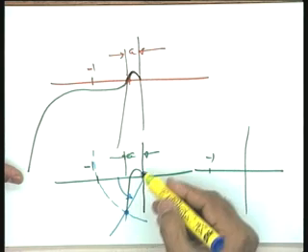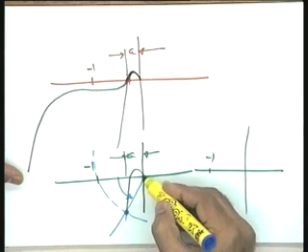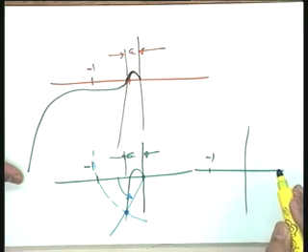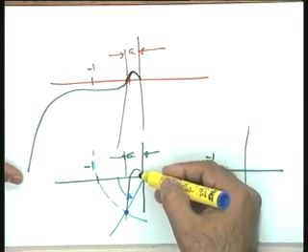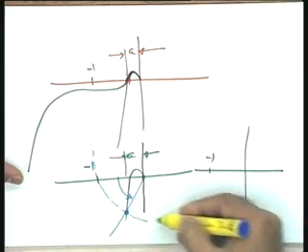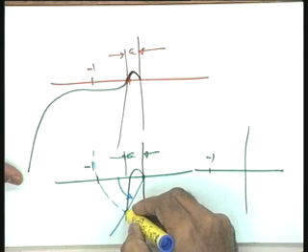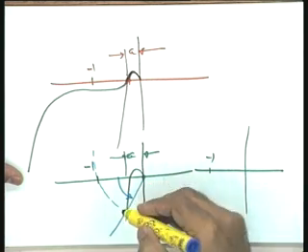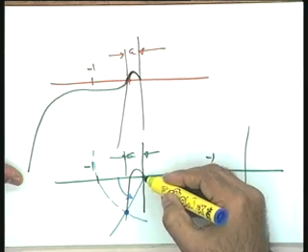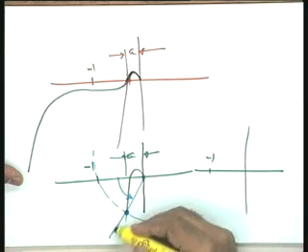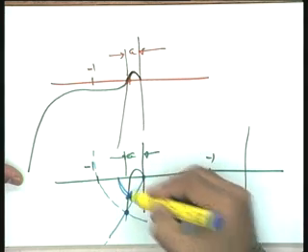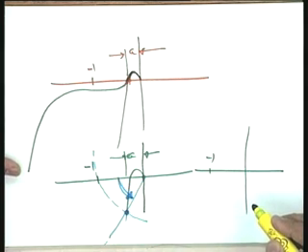I again repeat, the point on the plot where the magnitude is equal to unity is located, which is equivalent to saying that a unit circle passing through the minus 1 point, wherever it intersects your polar plot, is the critical point you want to consider. So, this particular point is taken, you draw a line over here, and this angle gives you a measure of the distance with respect to the minus 1 plus j 0 point.